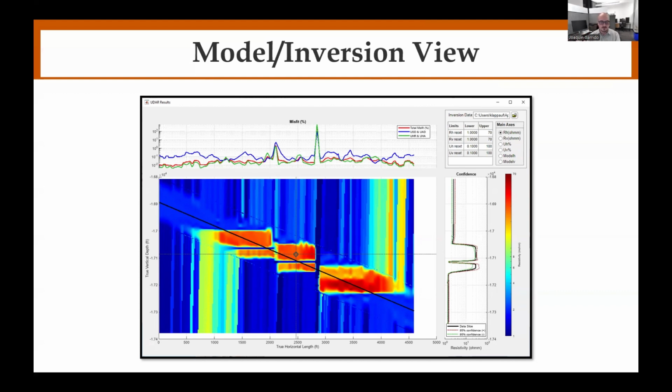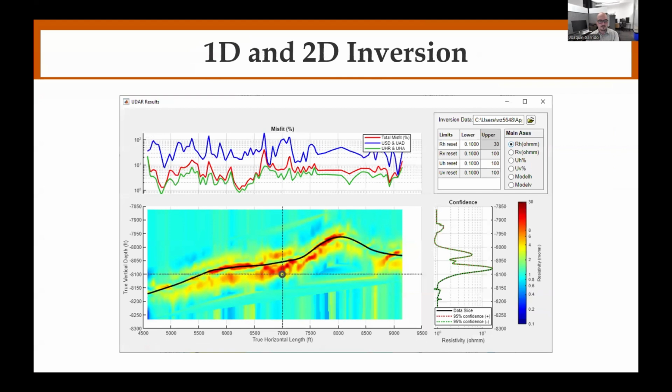You would never just look at any one measurement and say, okay, this is the apparent resistivity. You need to really perform the inversion and estimate the resistivity at different distances from any of the measurements, and you need to combine them all. We have the capability of performing this inversion and forward simulations for 1D and 2D. We're working on the 3D. We have done this with field data and so on.